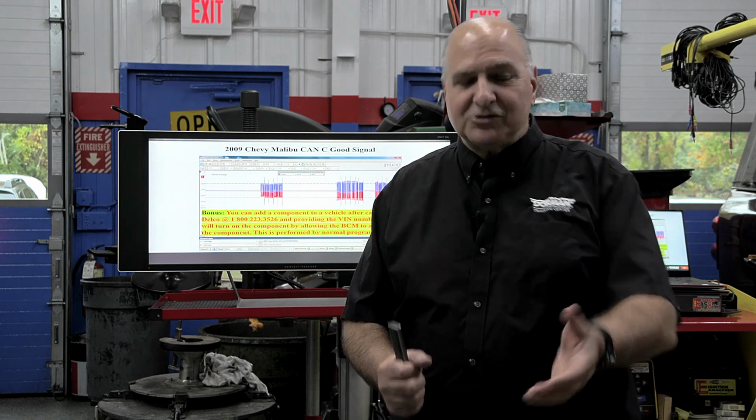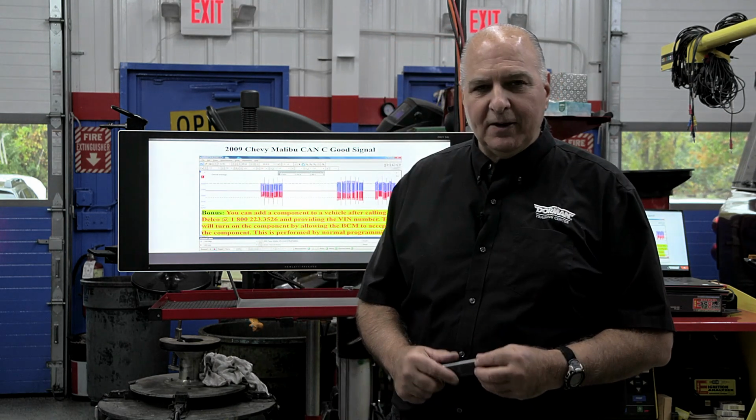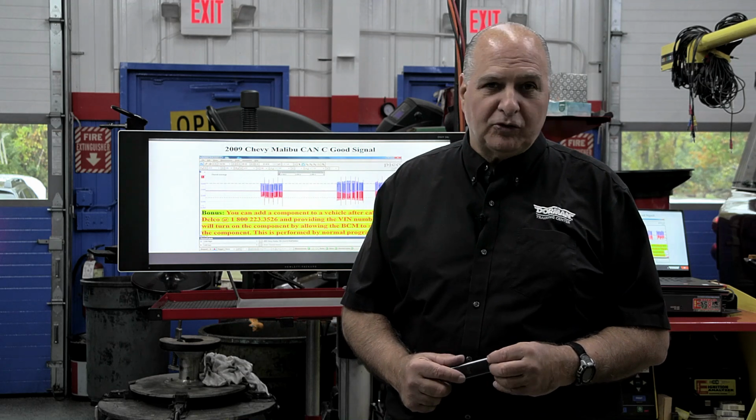The owner of the vehicle asked the body shop, hey, can you put fog lights? I didn't buy it on the vehicle, and I really want those fog lights. They ordered them from GM, put them in. They didn't work. That's right, they didn't work. Why? Because it's somebody new on that bus, and it needs to be programmed in there. So we told them, yeah, no problem. Just bring it over. We'll get this thing done, 1, 2, 3. Well, it wasn't 1, 2, 3.